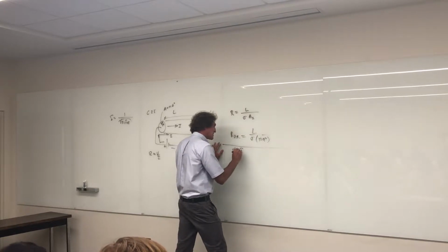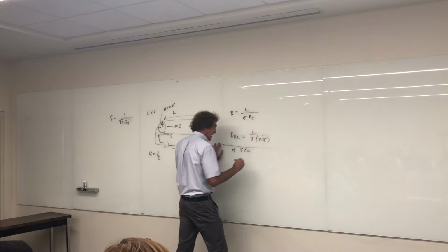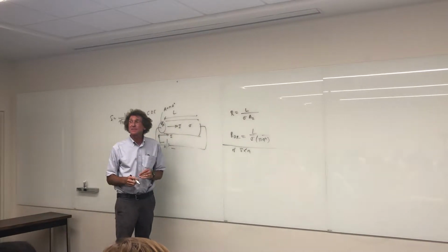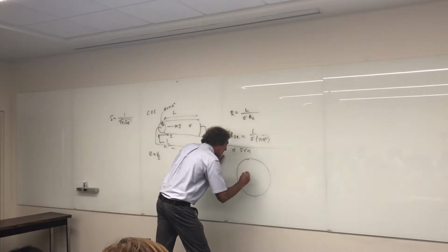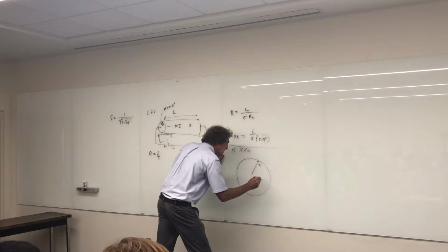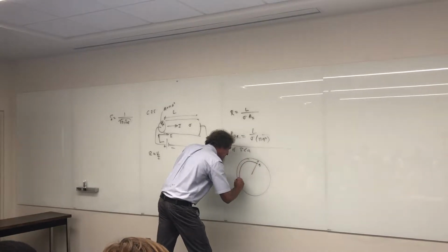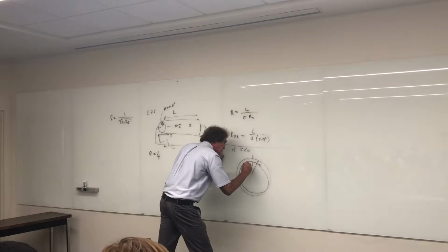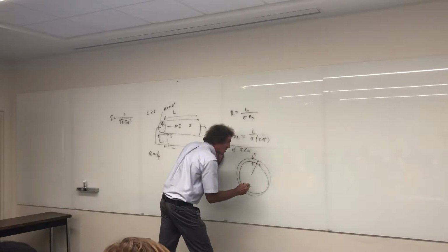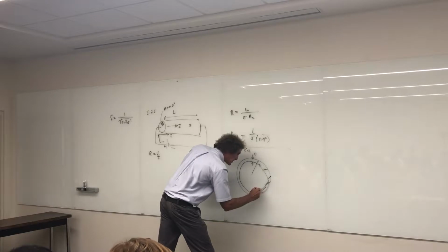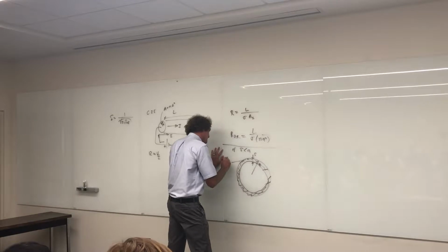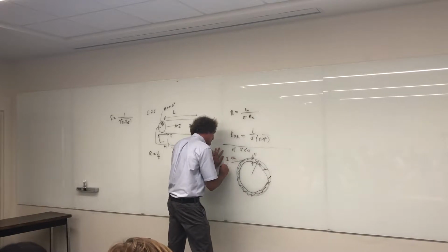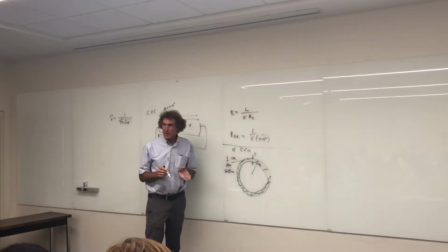If the skin depth is less than A, in other words, less than the radius, then what you have is this. If you look down the pipe of the actual wire, here's radius A, and if we go in 1 skin depth, this would be a skin depth. That means all the current would flow in that skin depth, on the surface. Does everybody understand that?